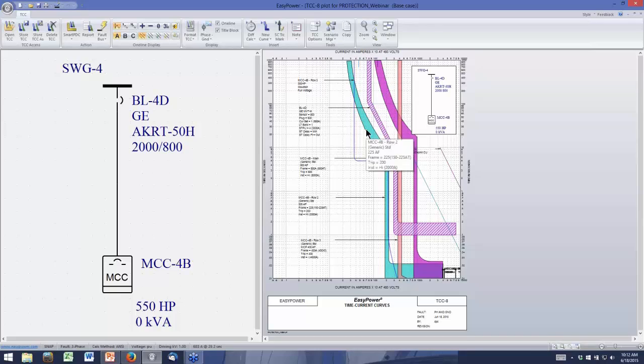Row 2 is the SubFed device that feeds panel 3. It shows up because I defined it as a SubFed device, and we defined that breaker information. So again, you can have as many devices inside the MCC defined as with TCC, and they will all show up anytime you pick this MCC and plot it.